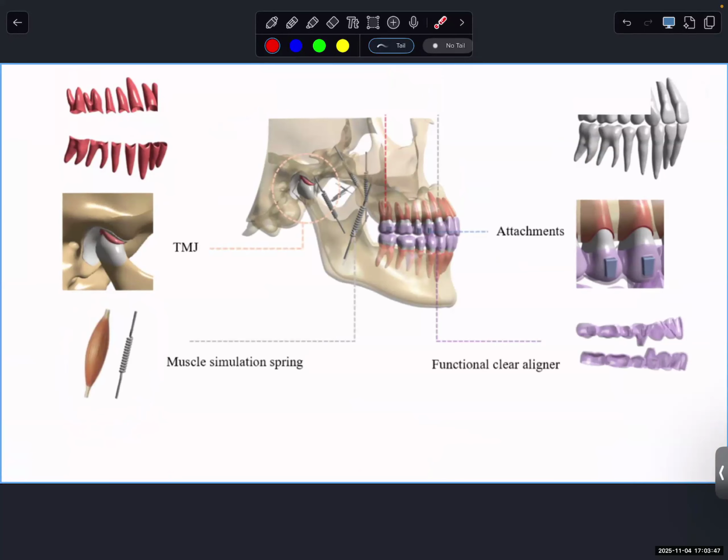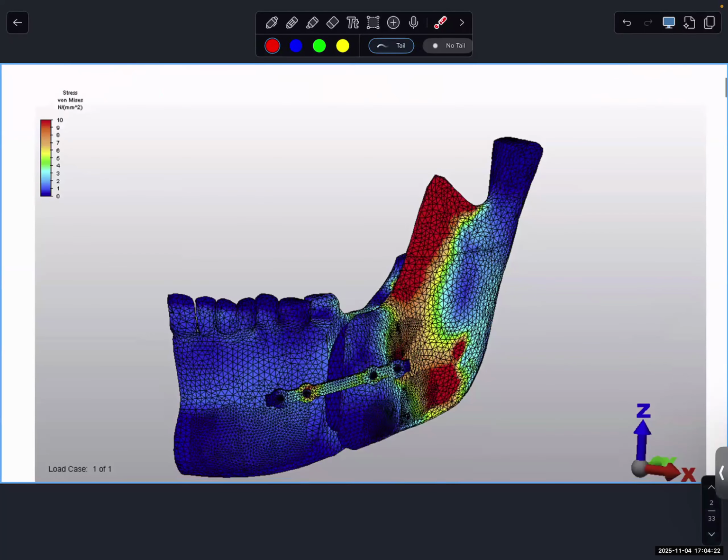In mechanical engineering, it's all about math. In terms of math, the muscle functions the same way as a spring. Probably all of you learned in high school or middle school physics that F equals K times X. That is the spring system, and you've got to remember that one. K is the stiffness of the spring system. For the muscle, if it's an elastic material that can only carry axial force, tension or compression, mathematically it's the same: still F equals K times X. That's why in FEA we can use a spring system to replace the muscle. We can talk about it in more detail later.